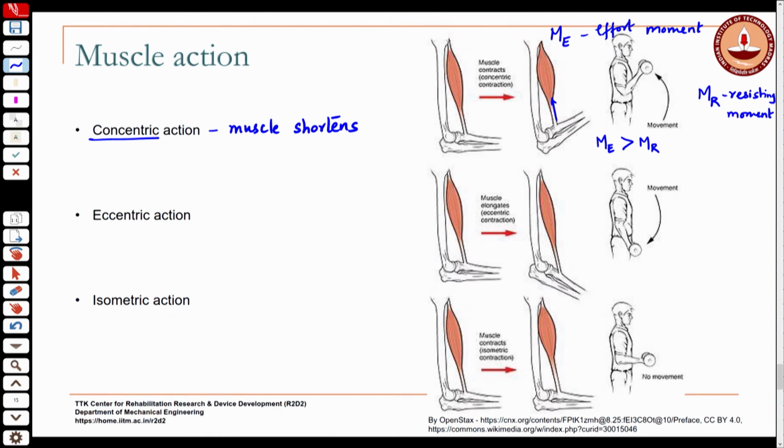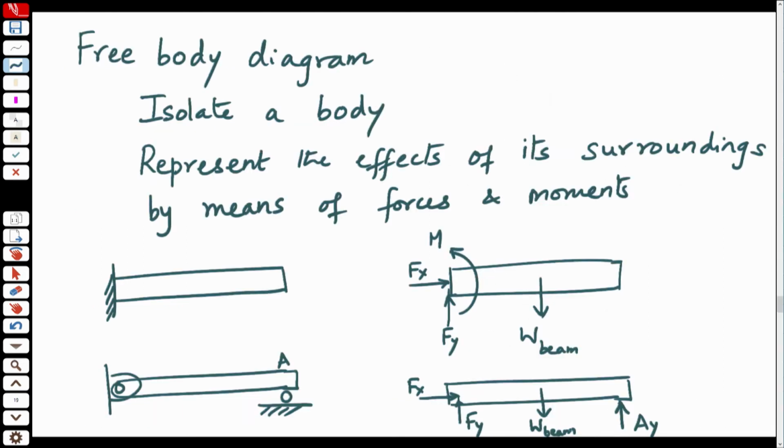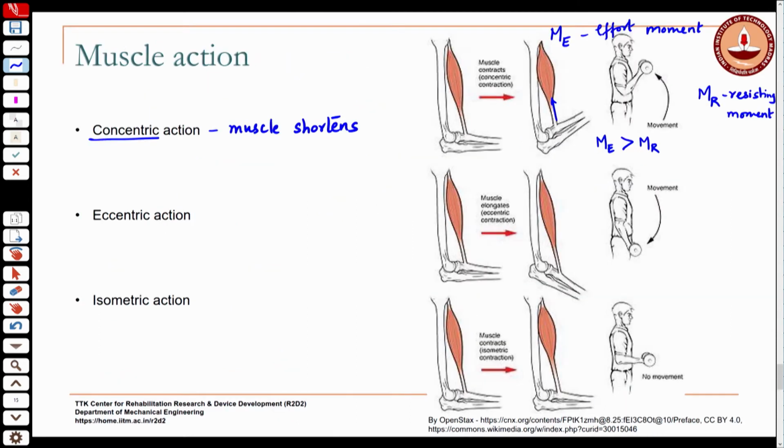So, when we draw a free body diagram, if we do not know the directions of the unknown forces, you express them in terms of components in a known direction, be it x and y or whatever else you take, two orthogonal components. On the loading of the beam, whatever unknown forces, the signs get determined based on the overall equilibrium.